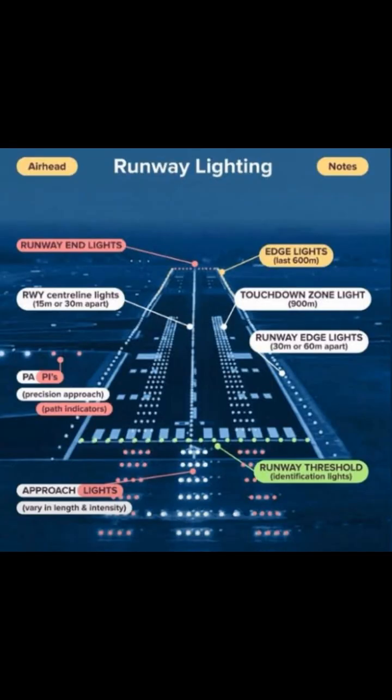Airfield lighting system. An airfield lighting system has many miles of circuit cable. The system has miles of cable originating from the source of power to the runway, plus the distance around the runway itself. The only practical way to light a runway and taxiway system is to use the series circuit principles. Figure 6-7 illustrates how large the system may be.